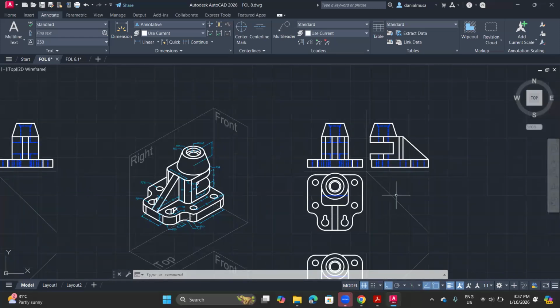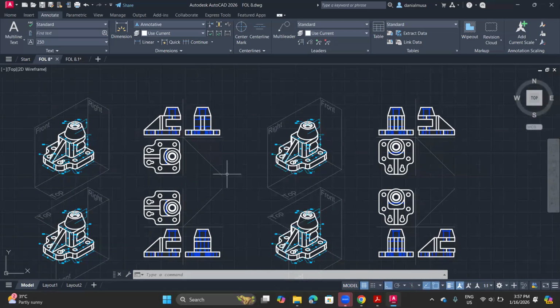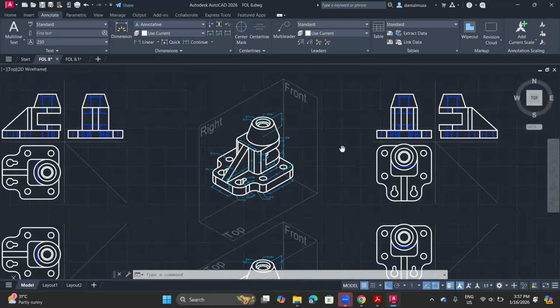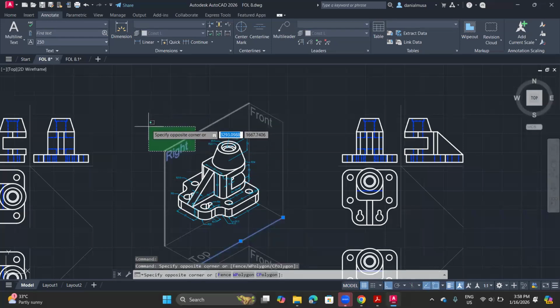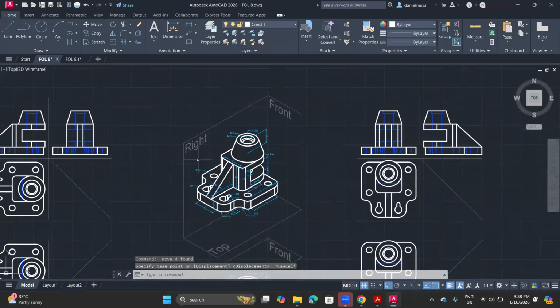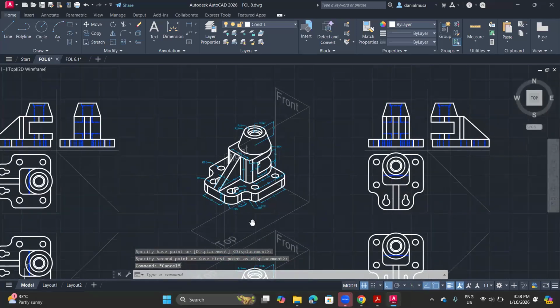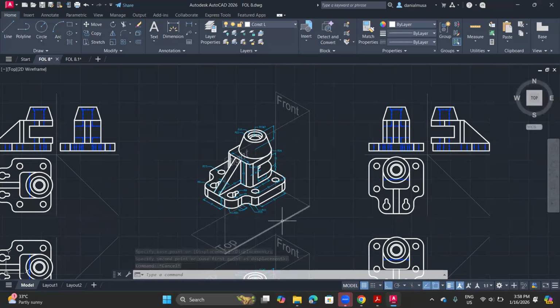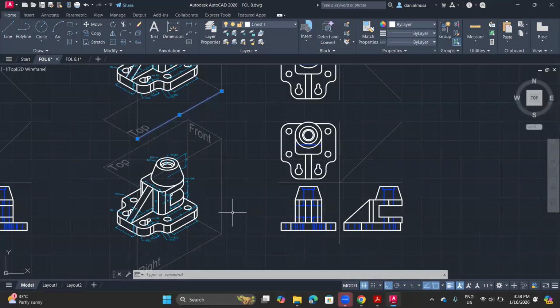But for this, you can imagine the angle like a box. You are opening the box. For this one, I am opening the box from here. So the right view is, let me move on. So I am looking at this object from here, the first angle to here, so it opens like this. And for the third angle, it will become like this. The shape is somehow like this.